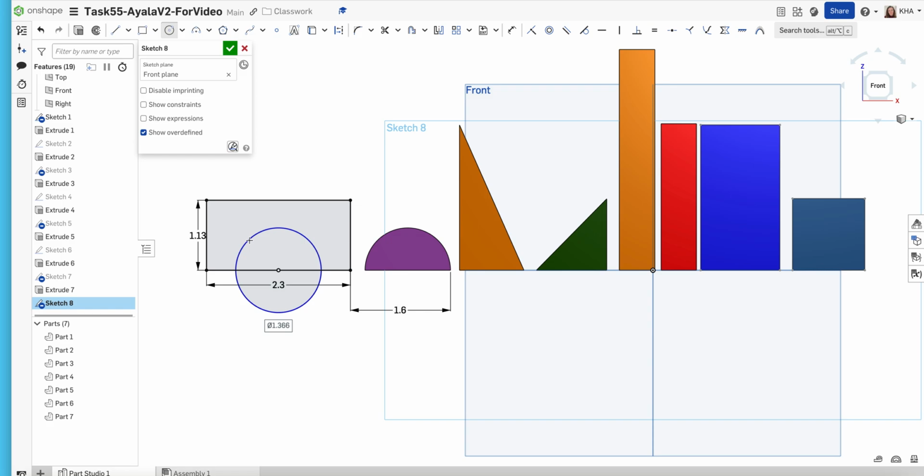There's my circle, and what is the diameter of this particular circle? I'm going to use the small jaws of my calipers since I'm measuring the inside of something. So make sure you're using the jaws on the top of the caliper, not the bottom. We often use the bottom to measure the outside of something. I'm not going to put in an accurate measurement because I want you to look this up yourself with your calipers.